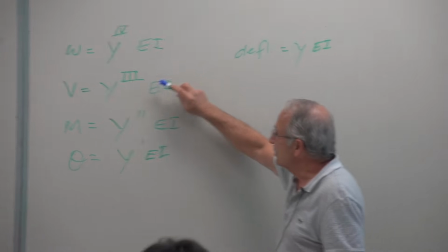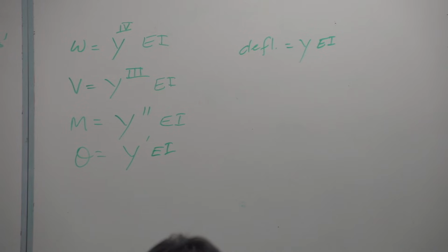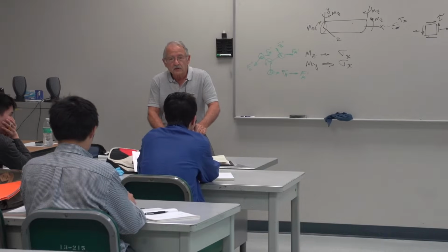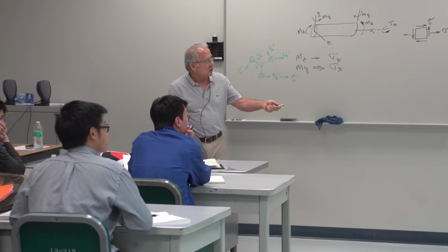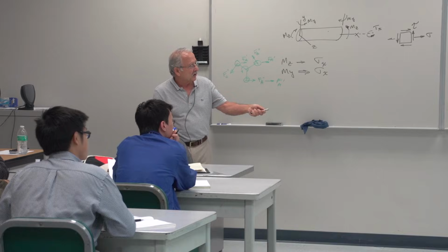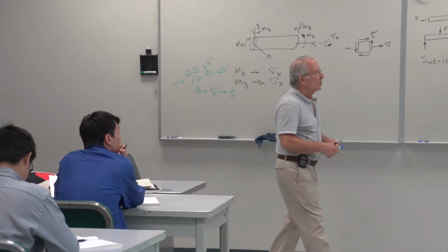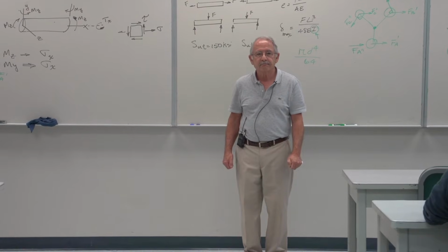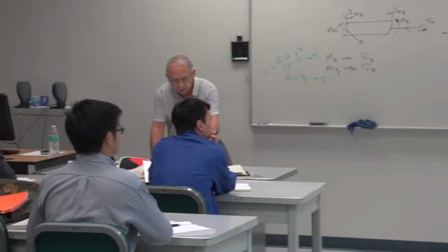So you can say this is the slope of this one, that's the slope of this one. Exact relationship that exists between any two of these adjacent to one another can be transferred through the whole thing. So you can actually draw these diagrams without writing any equation, so long as you can calculate, for example, area under that diagram, because that'll be the change in the value, in this case, of the deflection. Any questions? So that's another point that I wanted to come up with.